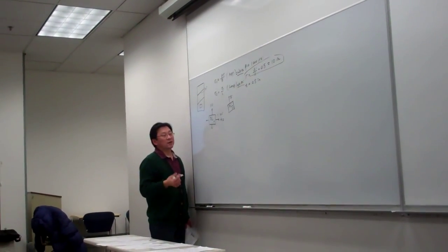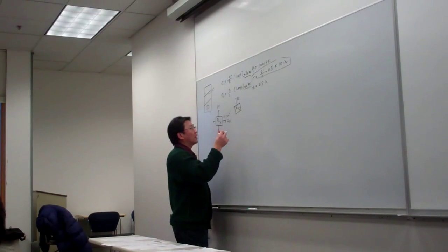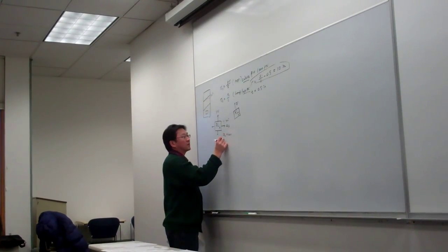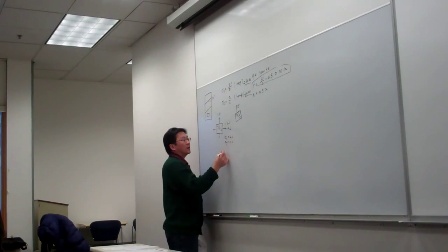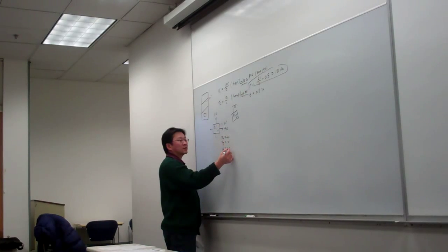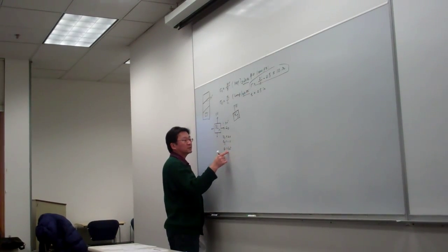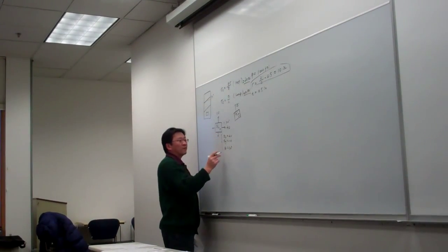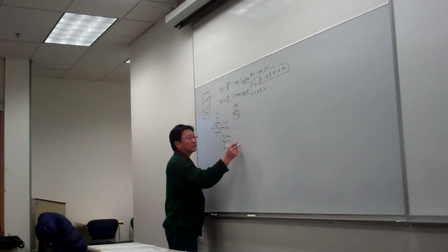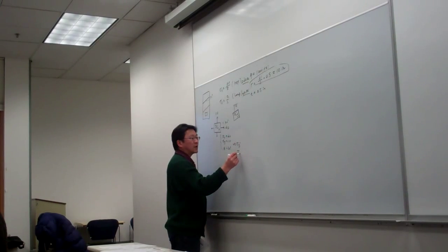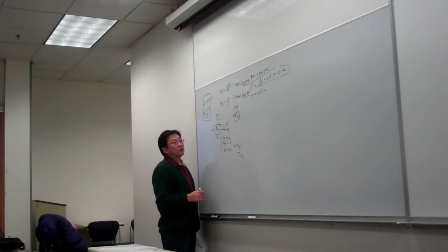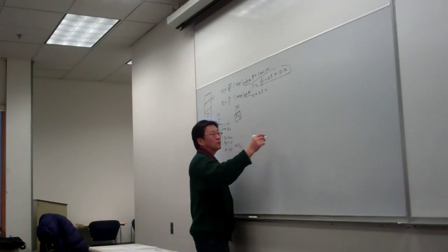So either you take up the formula, given sigma X equal to 20, sigma Y equal to 10, and theta equal to 30 degrees, because these are counterclockwise, so that is positive. You plug the three values into the calculation to get sigma Y prime and tau X prime Y prime. The two values will give you the answer. Or otherwise, we can take up the Mohr circle.